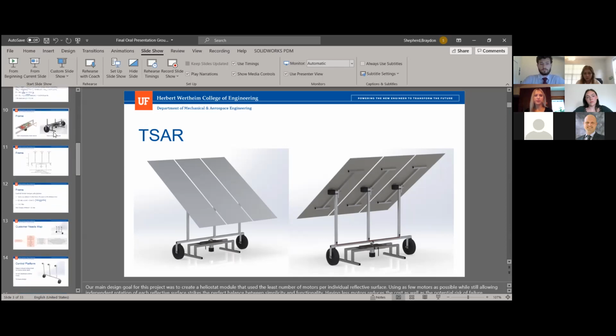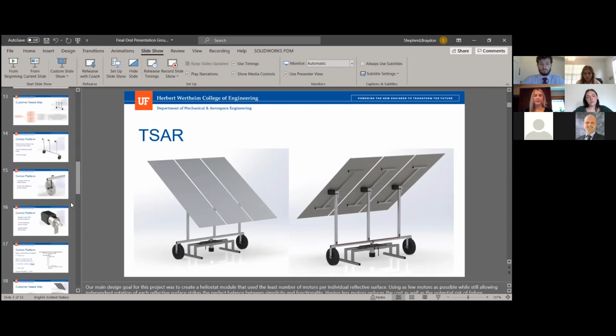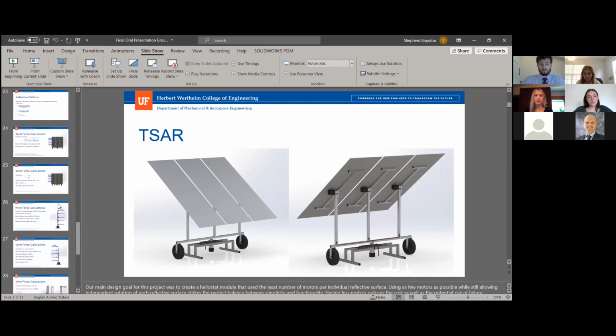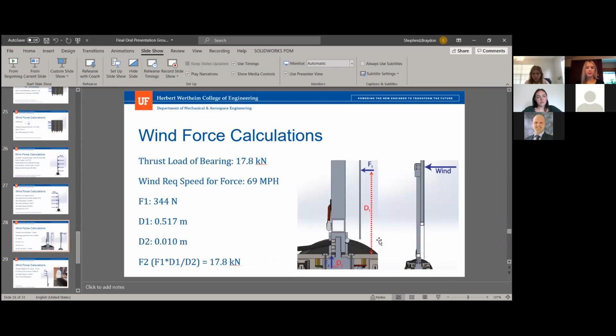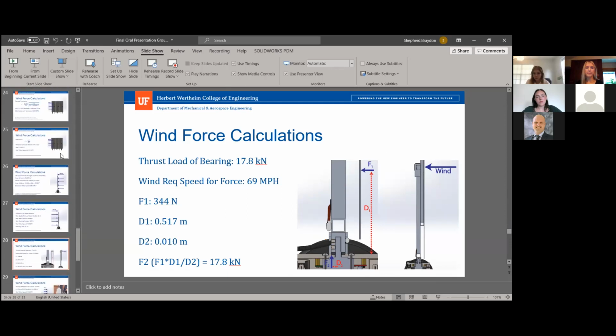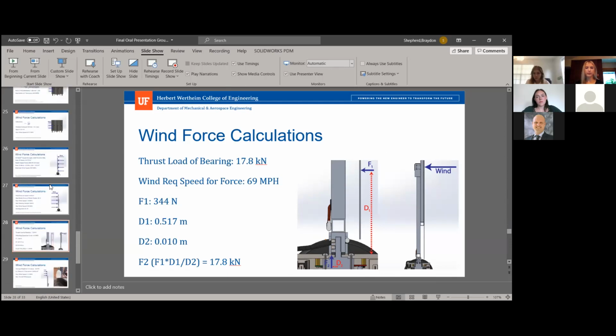And I wonder- Yep. So we've actually performed a calculation of the maximum wind speed that the motor shaft could sustain in this direction. If you go to the slide down lower there. I think your question goes along with Mr. Singer's question about the two wheels, because we have the wheels side to side instead of front to front, and that would mitigate the force on those mirrors. But we did a calculation. This is the calculation on this central motor shaft. So the wind is hitting the mirrors, and we have this bending moment on this shaft.